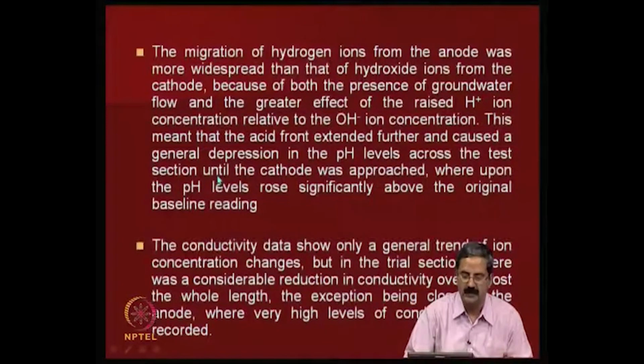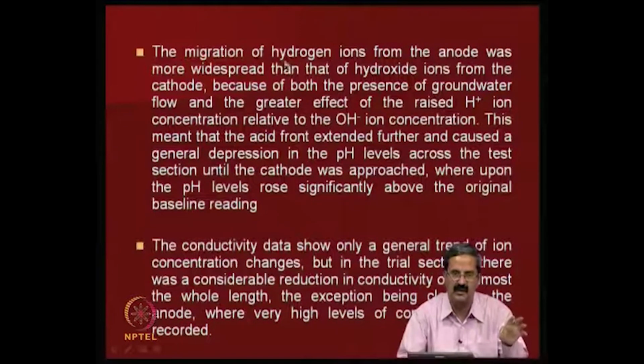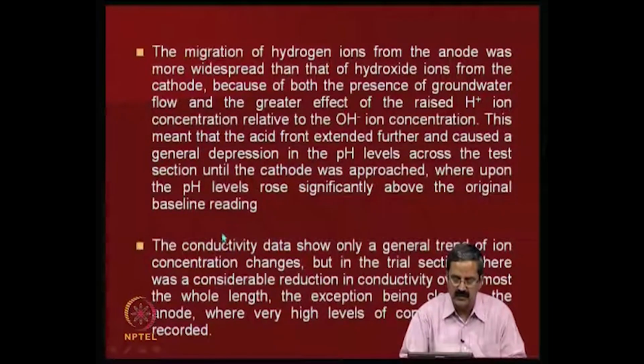So, based on the pH measurements, they were able to say what the area is that is more acidic or more alkaline. This is a very important observation, particularly when you are talking about buried pipes or objects, and you are trying to do dewatering close to buried objects made of steel. One should really look at corrosion and pH and all that.